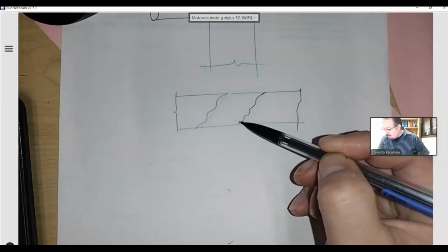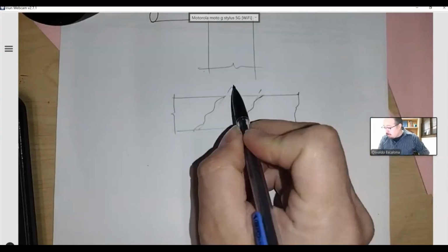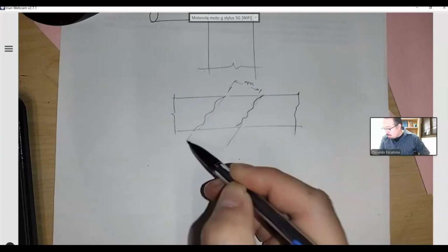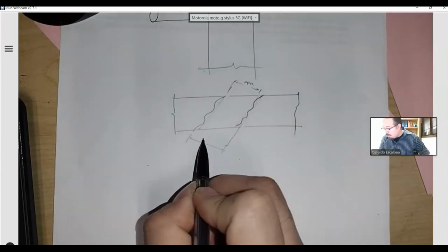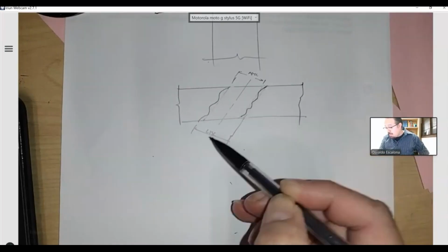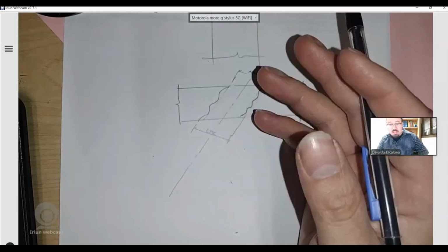I can still have the MMC, which will be the smallest I can get. Let's put it here. MMC. And you'll still have the LMC, which is the biggest the hole can get. And I can also have the center axis once I expand, the same way that I grab the bolt and squeeze on it and define an axis. I can do the same concept with the shaft.